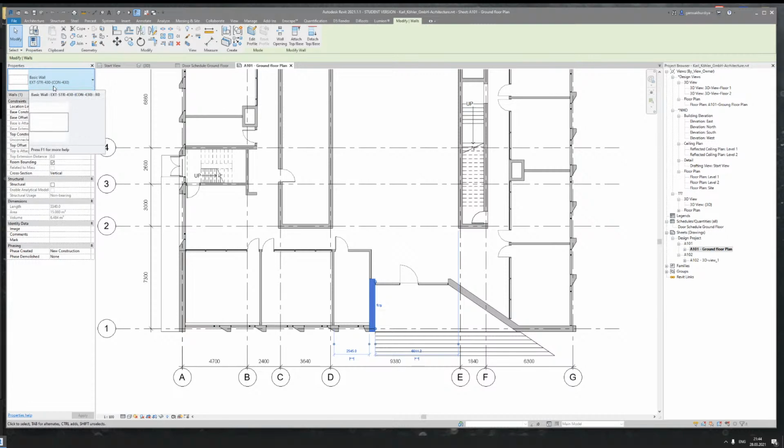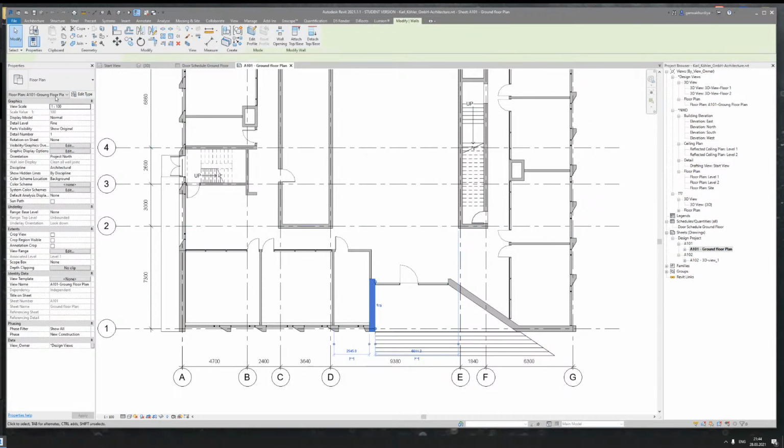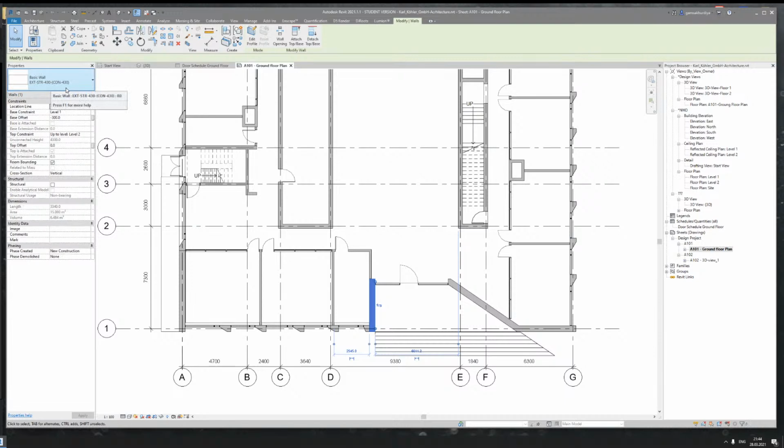If someone sends me this model and I click on this wall and see this naming, it clearly shows me that the person who did it really understands what BIM is. Because they made a really structured name: the exterior part, structure wall, overall width of the wall, and inside the wall what we have, like concrete 430 millimeter. Only by this naming, I understand who did this model.